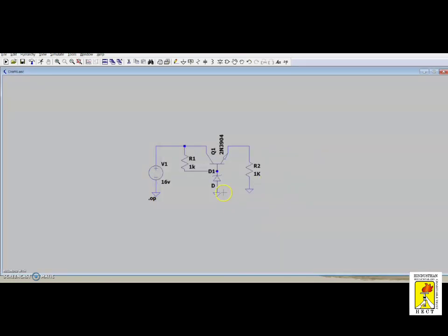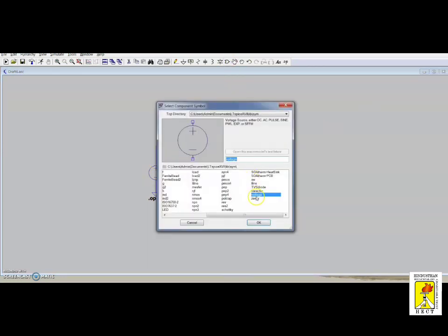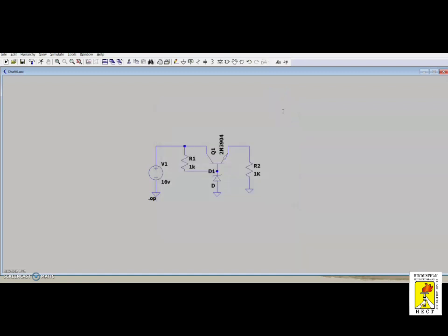Place it over here and select a voltage source. Go to voltage, select the voltage source and place it over here. Then select the resistor and place it over here. This series voltage regulator circuit diagram is very typical, as we had seen in the previous circuits, like analysis of common emitter amplifier, and it is easy to pick and place all the components.